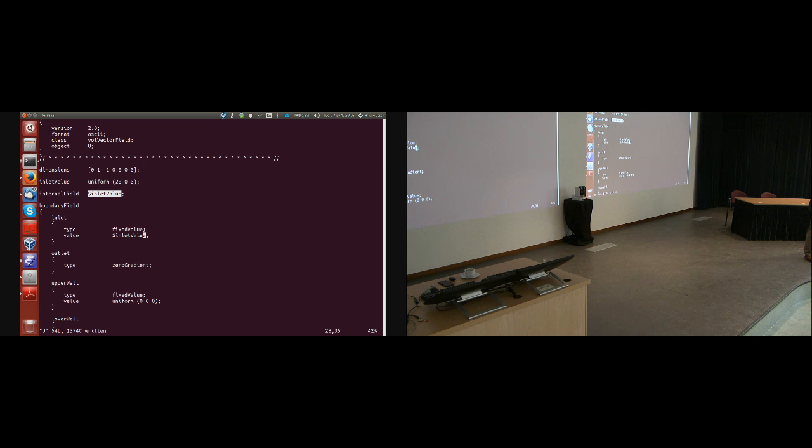Okay, so in foam, we want to use a boundary condition which will do the same, but we cannot talk about outflows and inflows at the boundary because the library doesn't know what equations it's solving. So for that we will use a special boundary condition called inlet outlet. What that does is it says if the flow is going out, use the zero gradient boundary condition as normally, which is what I would have here at the outlet boundary. But if the flow is coming in, then use the fixed value to a certain value. Okay? So let's just change it.